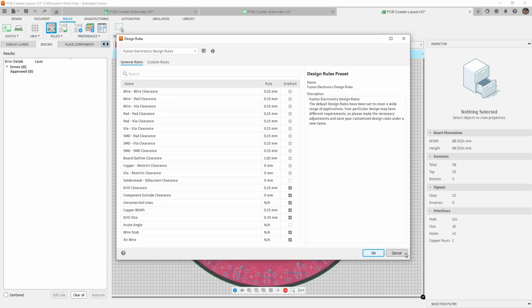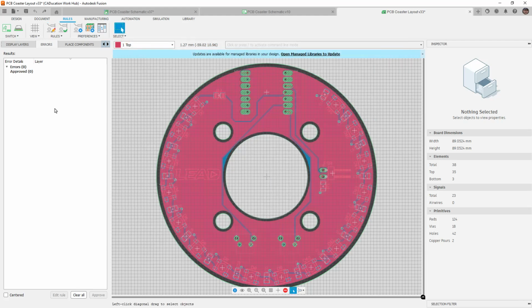If you leave everything as default, then this should automatically be turned on and you don't need to worry about it. However, if you do turn it off, then you would want to make sure that you go through the process of doing the design rule check. So basically, you would click this button, and it would run through and validate whether or not there are errors. I'm going to go ahead and delete one of these again so we can run through it. And then it would just display here. Basically, it would tell me that I've got this unrouted section.